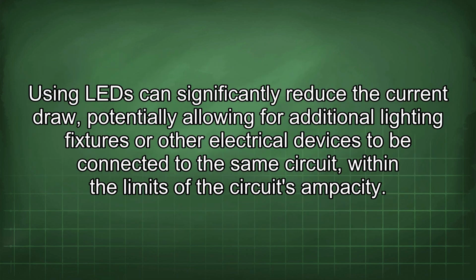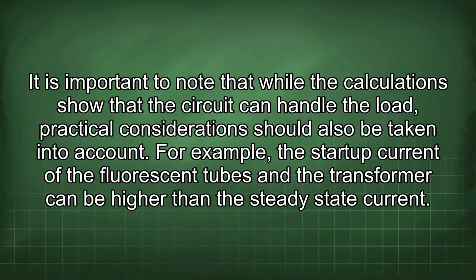Using LED can significantly reduce the current draw, potentially allowing for additional lighting fixtures or other electrical devices to be connected to the same circuit within the limits of the circuit's ampacity. It is important to note that while the calculations show that the circuit can handle the load, practical considerations should also be taken into account.